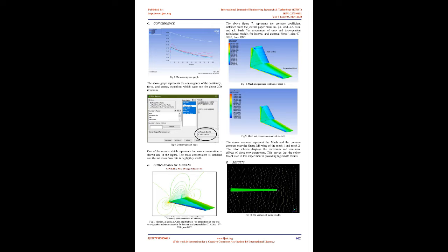As this is a mesh-independent study, the meshing of the domain is done twice. In the first case, the number of elements obtained is 360,895. The second mesh consists of 652,384 elements. The setup details for this case are pressure-based and a steady solver. The viscous model appropriate for this case is Spalart-Allmaras, along with the energy equation.